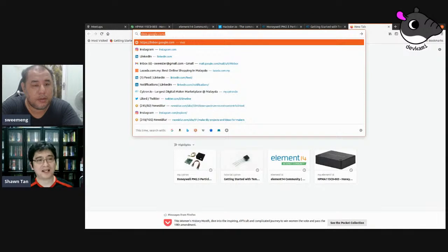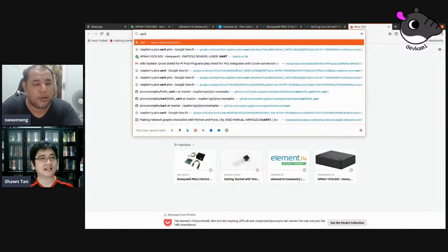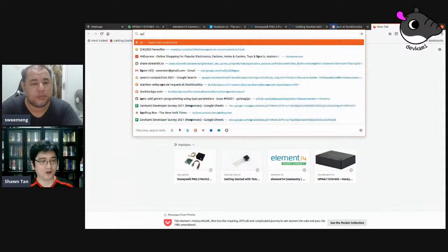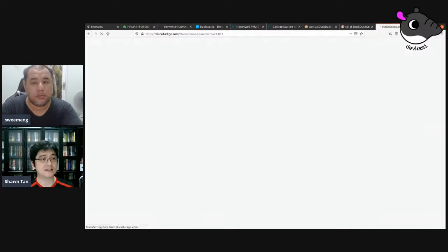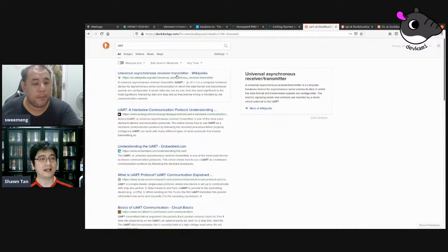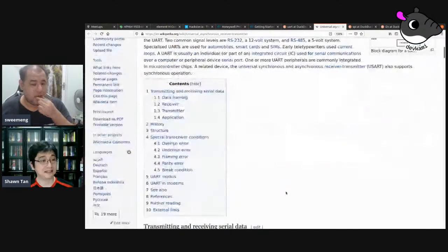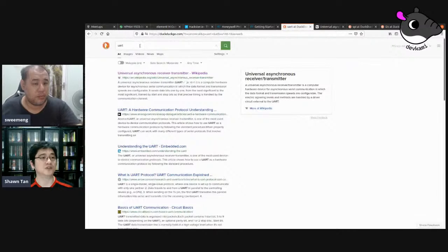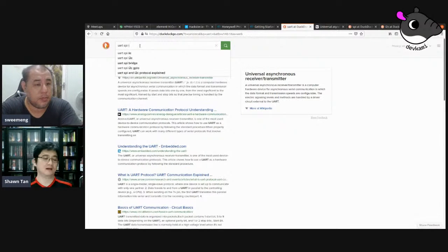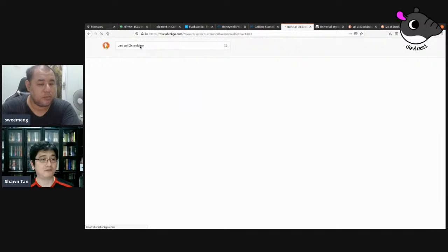All right. So we have UART, SPI, I2C. These are the very common protocols. If you are going to classify them, you want to look at the differences that matter to hardware, basically. For hardware guys, number one is how many pins it takes, because the more pins it takes, the more pins you are using on your microcontroller. Then the nature of the communication, whether it's simplex, half duplex or full duplex, and then also of course the amount of bandwidth available.